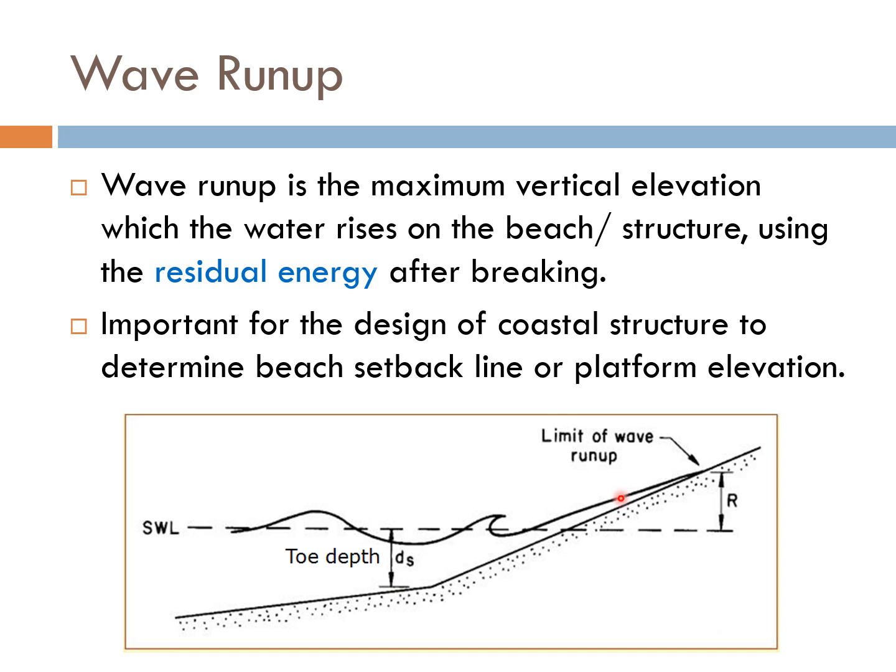And if we build any structure, we will want to make sure that our structure has a crown level which is higher than the run-up point, so that the water doesn't go over the structure to flood the inside or the land side of the structure.